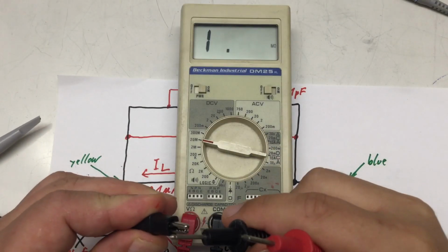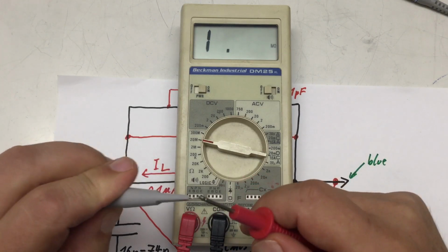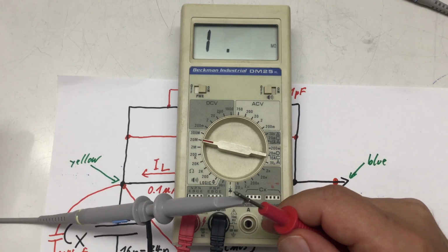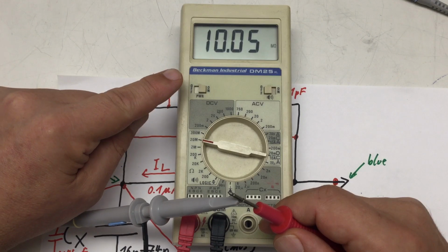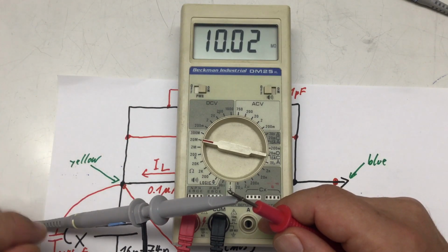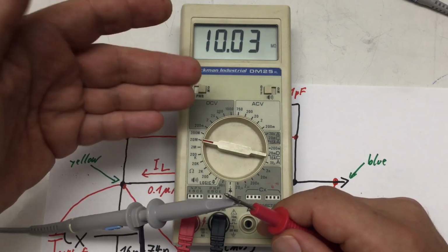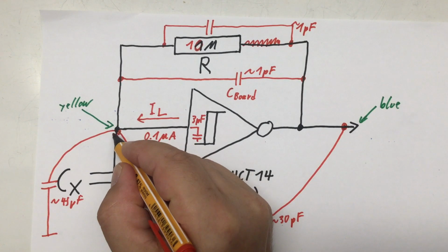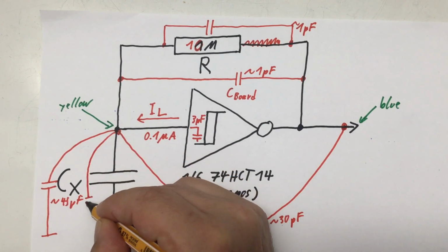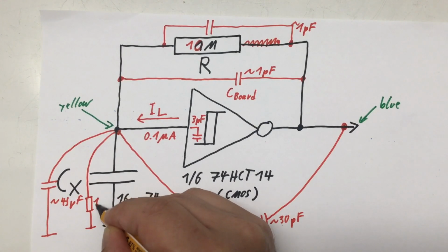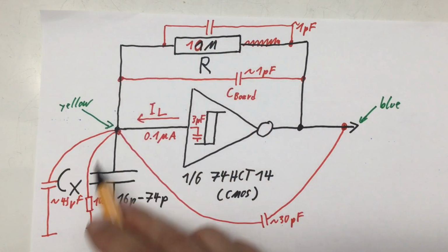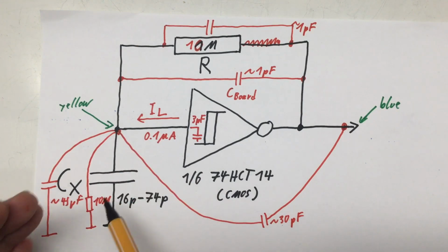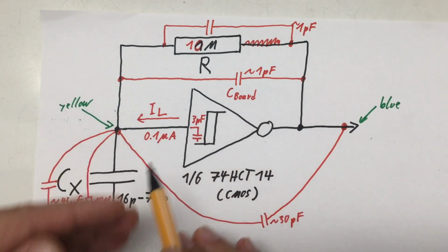Let's measure also real quick the resistance we have here. That should be about 10 megaohms. And yep, that's about right. It should be 10 megaohms because I put my probes to 10 to 1. It's pretty much spot on 10 megaohms. So the probe on that side also introduced a parasitic resistance to ground of 10 megaohms, and we're charging the whole system over 10 megaohms. So that really also had a significant influence on how the whole thing behaves.